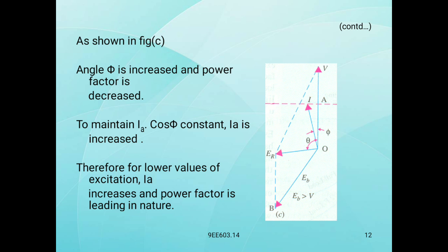Here is the phasor diagram for over excitation. IA is moved in the anticlockwise direction, and similarly ER also moves in the anticlockwise direction.